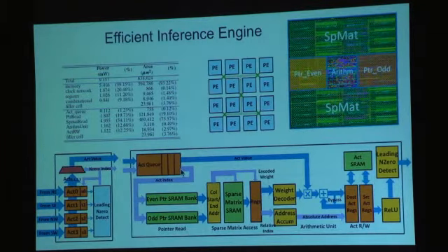We chose to look at how we could take these compressed networks and deal with them. So with the compressed networks, even without eDRAM, we're able to take a pretty sizable network and hold these sparse matrices in on-chip SRAM. And these sparse activations are held in pointers in this arithmetic section here. These are the destination activation pointers and the source activation pointers. And by storing the matrix in a compressed sparse column format rather than compressed sparse row, we're able to exploit the dynamic sparsity of the activations by doing a distributed find first non-zero.